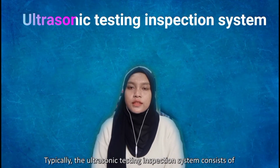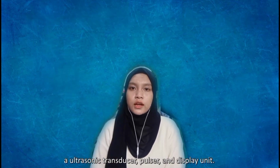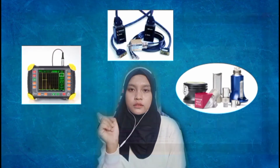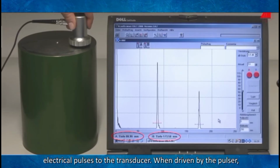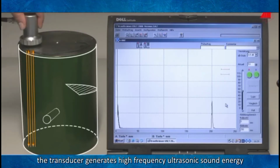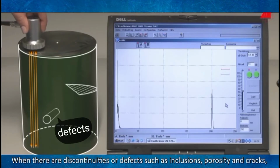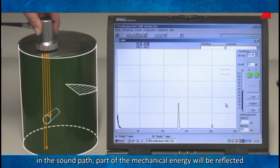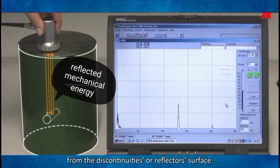Typically, the ultrasonic testing inspection system consists of three major components, which are an ultrasonic transducer, pulser, and display unit. A pulser is an electronic device that can produce high-voltage electrical pulses to the transducer. When driven by the pulser, the transducer generates high-frequency ultrasonic sound energy into the material in the form of sound wave. When there are discontinuities or defects such as inclusions, porosity, and cracks in the sound path, part of the mechanical energy will be reflected from the discontinuities or reflector surface.